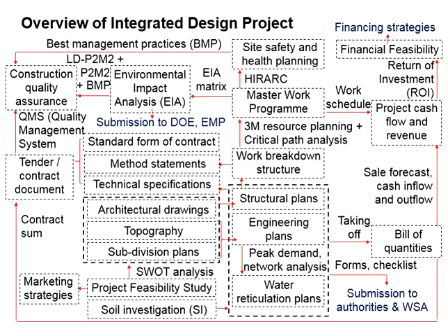Typically, in the structural plan, there are floor key plans by the number of stories: ground floor, first floor, second floor, and so on. In the floor key plans, it provides the details of the beams, slabs, as well as the columns. There are also foundation key plans, which can be shallow foundations like pad footing or deep foundations like pile foundations.